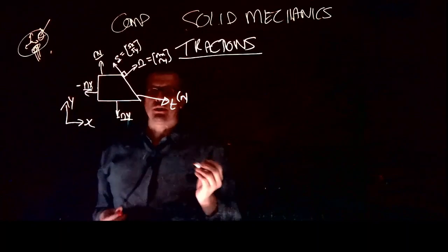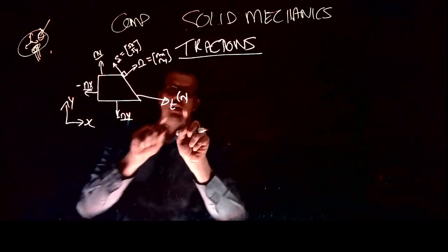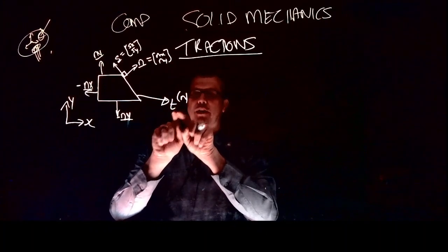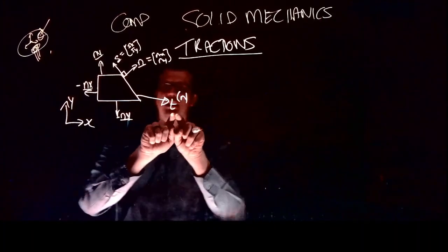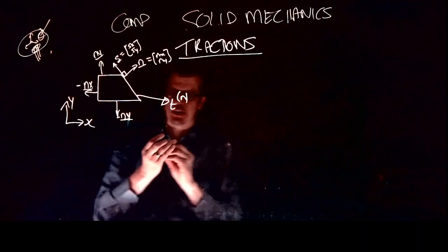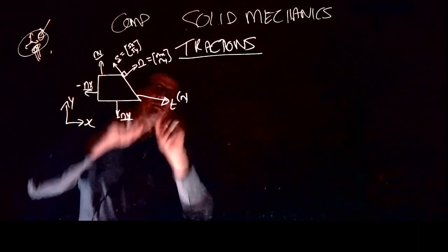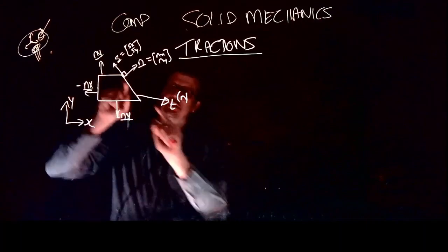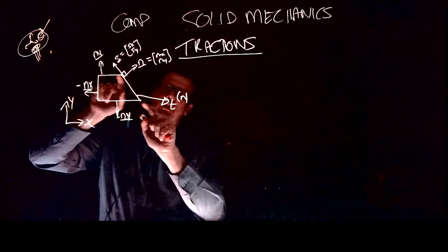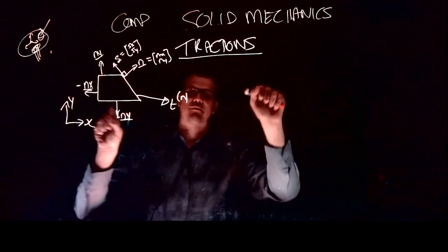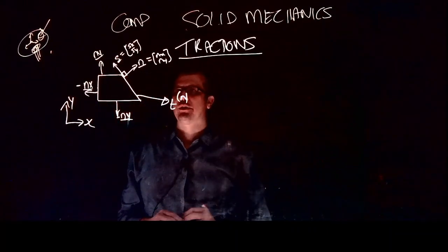And all I'm going to do is, this thing that we now understand, this traction, is just a force divided by area, in the same direction as the force. So by just looking at this, the force acting on this face is in this direction. And for the magnitude of that force, first I have to compute the area and multiply the traction by the area. Boom! And then I recover the force that I applied to that face. That's it. Nothing more than that.